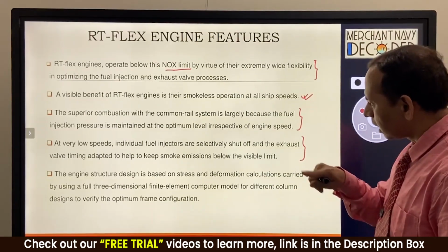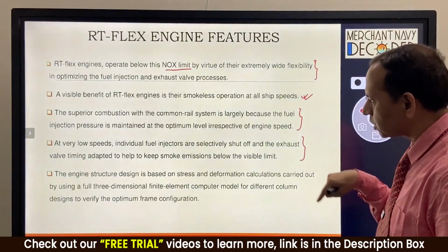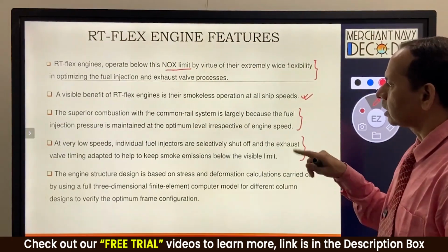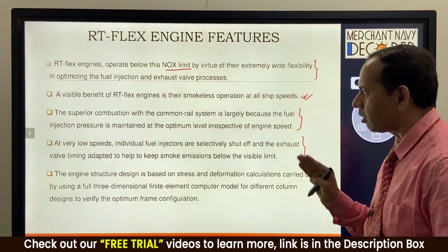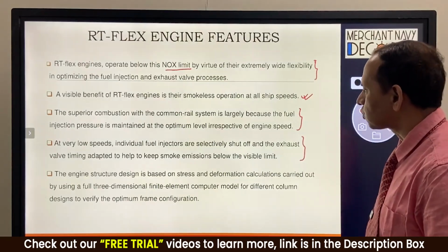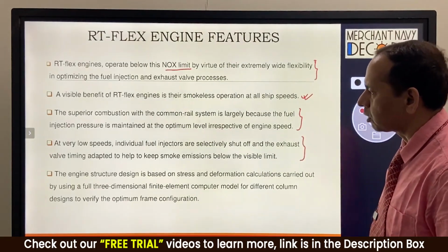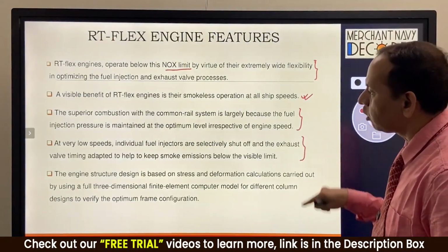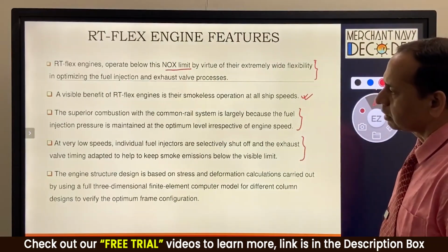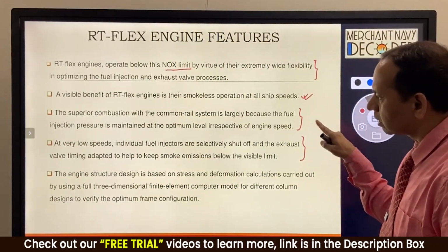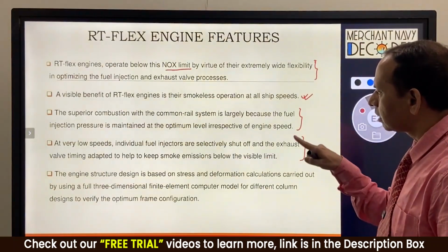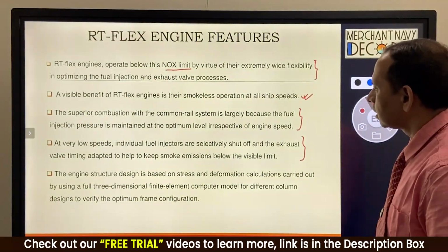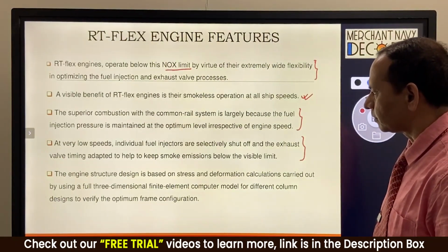This injector will keep on switching to a different injector progressively to ensure that the other injectors also remain within the stress, and the cooling is also done since they are not inoperative for a longer period. So at lower load condition, the injectors are also switching to a different one as per the direction from the VEX controller.